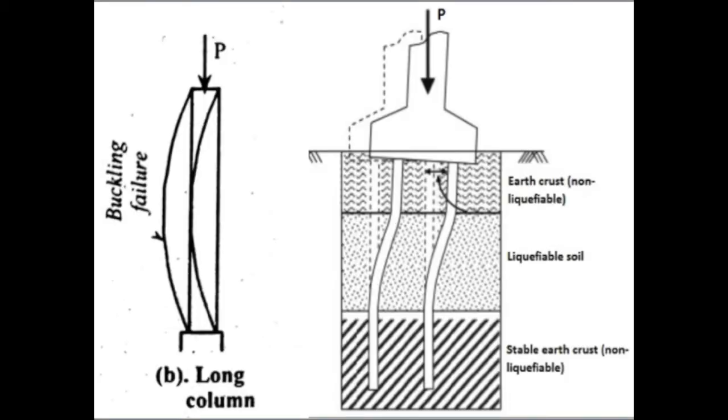Bhattacharya developed another theory based on buckling. He claims that the pile should be treated as a column that is taking on a massive amount of axial loads from the structure. Now the pile can act as a continuously supported column since it is surrounded by soil that continuously puts pressure on the sides of the column. However, when the soil liquefies, the pressure from the soil is no longer present. Therefore, the pile becomes unsupported and begins to buckle as shown in the figure on the left.